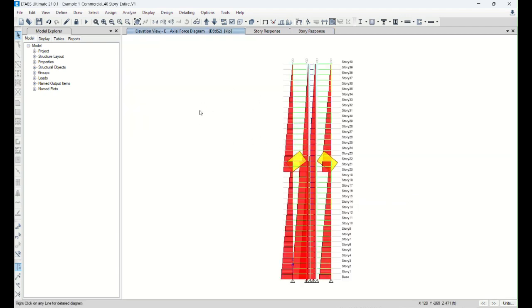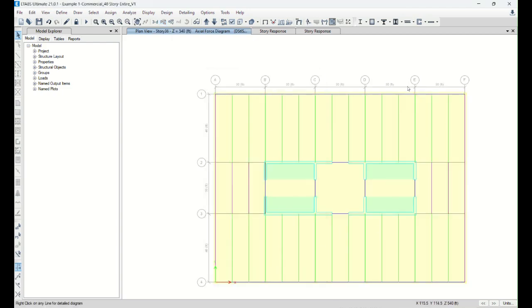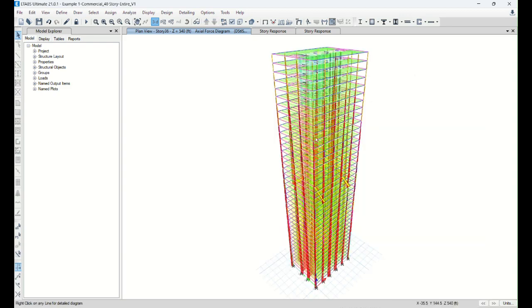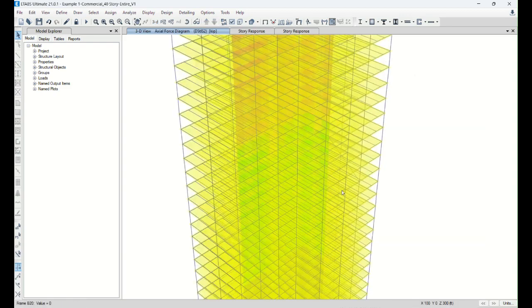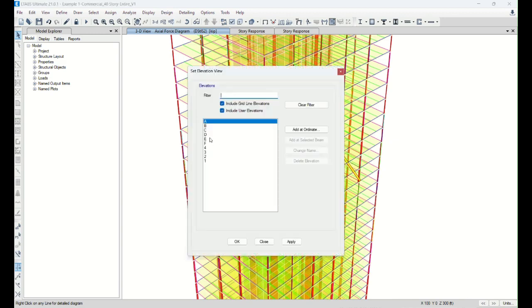So I think what you need to do is just look at your plan and choose the line of outrigger truss you want to add. Basically, exterior column, and you put the truss in order to tie the column to the concrete shear wall. All right, so I think you can manipulate and continue if you see that, okay, here are the actual forces under the gravity force, right? So 1.2 dead, 1.6 live. You know what? Let me show you one thing, that B line.